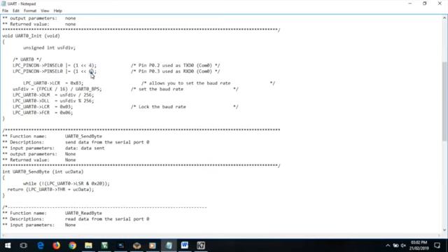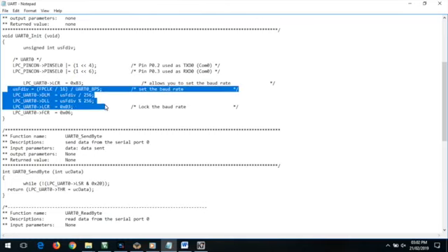And then pin number 6 has been set, that is port 0 third bit has been set. And then 0x83, it is because it's an 8-bit character length, and we are enabling access to the divisor latch. You can look into this LCR register, then we will understand why it is 83. Then using this clock frequency division, we are operating at 9600 baud rate.